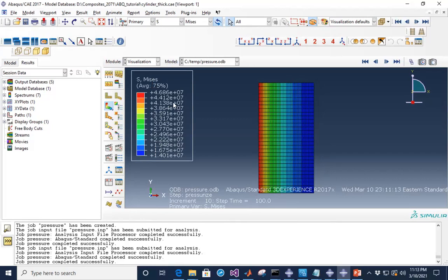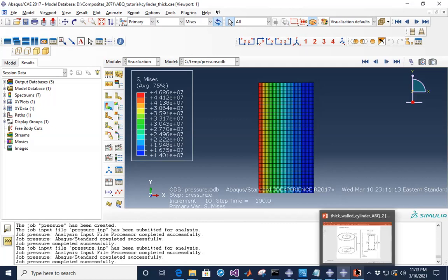So if you do 300 over 50, that is roughly a factor of safety of 6. So right now our pressure vessel is far away from yielding. So that's good. We can actually increase the loads roughly by a factor of 5 or 6 before it starts yielding. But right now there's no yielding in our body, which is good. But we can also look at some other interesting parts of the solution.